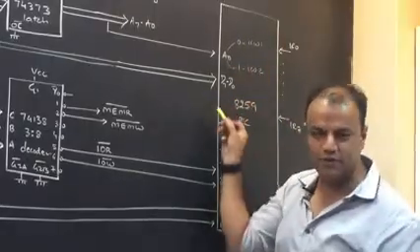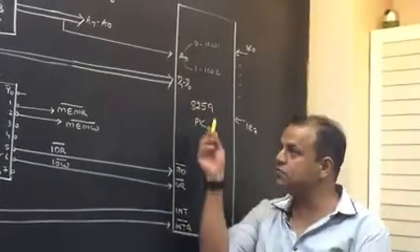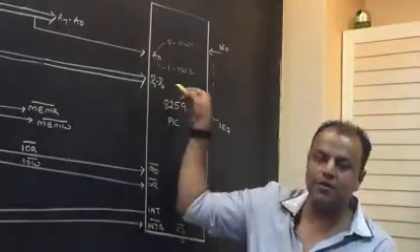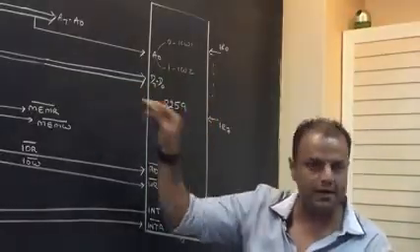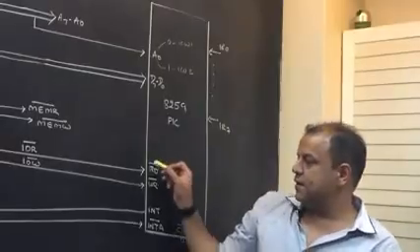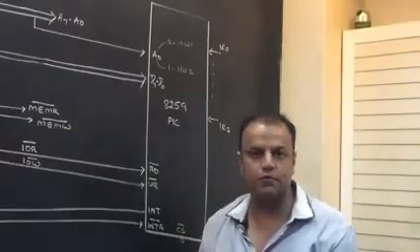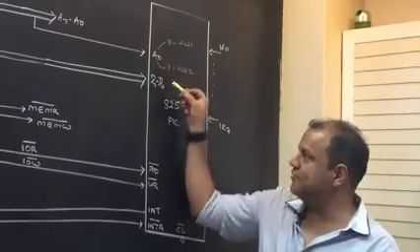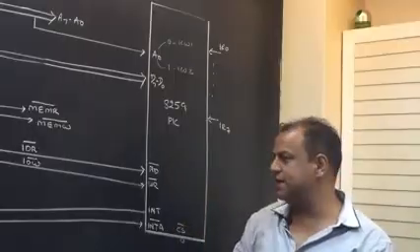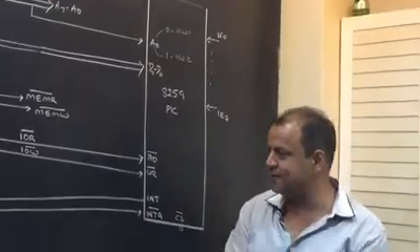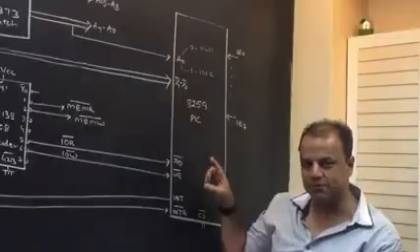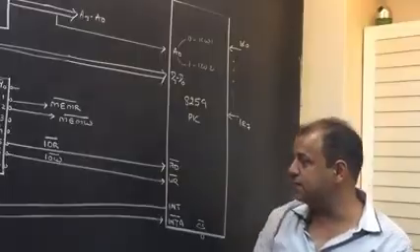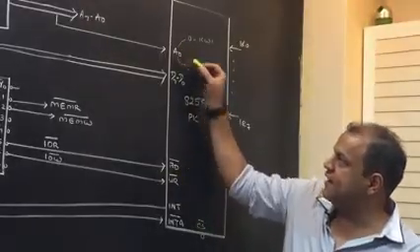So for that you need an A0, you need the data bus D0 to D7. Also, the data bus is bidirectional. From this data bus, what else goes on that side? The opcode of call, the lower byte of address and the higher byte of address. You know that, right? I'm sure you've seen the theory of 8259 before you watch the interfacing. That's the order in which you're supposed to learn. Now, there is address bus, data bus and control bus. For the control bus, we need read-write signals. In the architecture, there were read-write signals. Read-write signals decide the direction in which this data bus will operate. If the processor says, I want to read, data will go to the processor. If the processor says, I want to write, data will come from the processor.